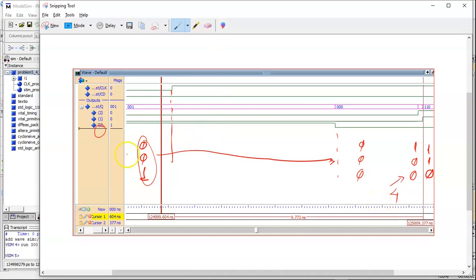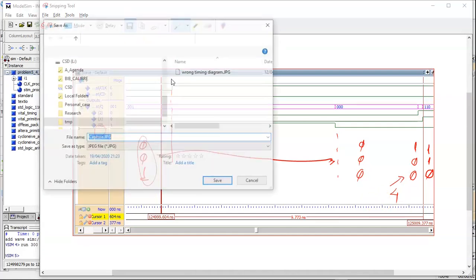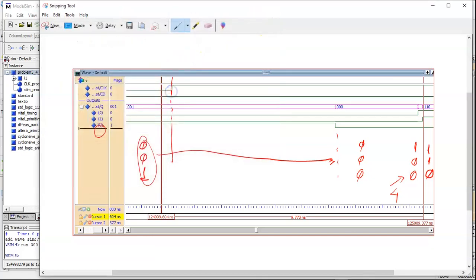So that's what happens in this period of time that goes from the rising edge of the clock to the final setting of the waveform. So here you have a period of time of 9.7 nanoseconds, and in between you have these two intermediate codes which shouldn't be here, right? And this is because the signals are propagating from the clock to the Qs, right? So that's kind of a final exercise about analyzing the waveform from the gate level simulation.